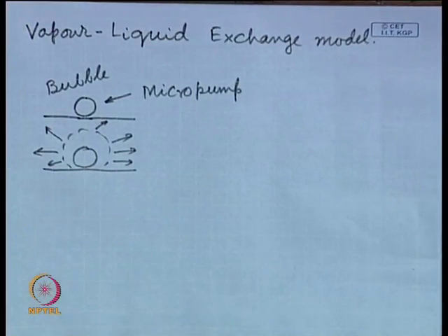When it is departing or collapsing, it is sucking fluid towards its center. And this growth and departure of the bubble keeps on occurring during boiling. So, we will have some sort of a pumping process of liquid due to the motion of the bubble. And this pumping process is mainly responsible for your heat transfer during boiling.